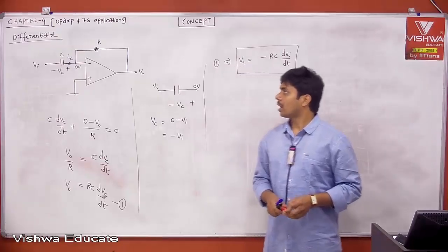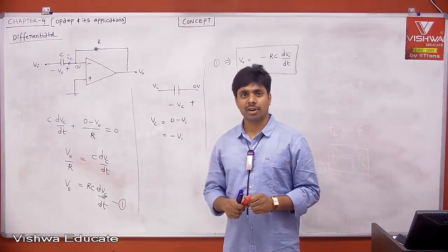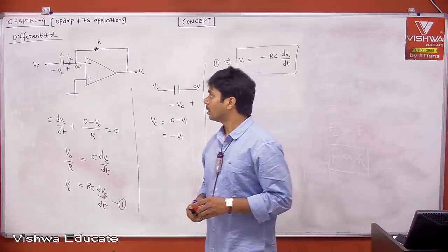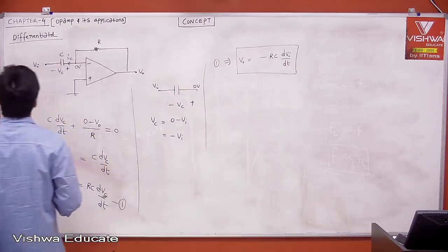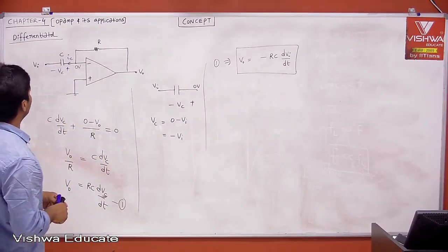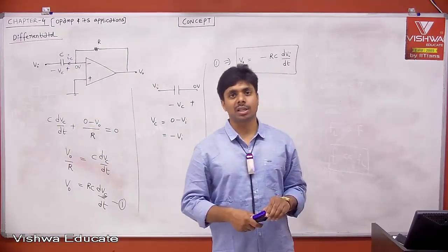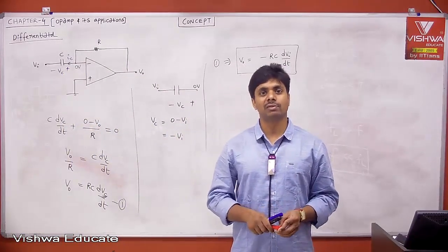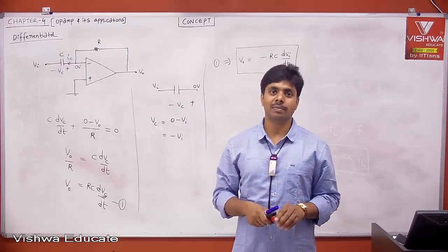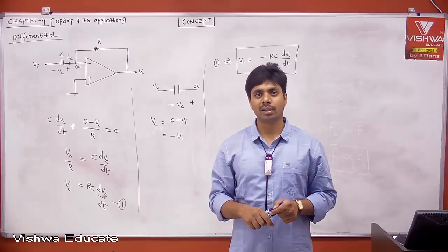That's fine. Now, in the last session, we covered differentiator. In previous sessions, we covered integrator, and while covering integrator and differentiator, I explained low pass filter and high pass filter, right? Then we can use low pass filter as an integrator provided the frequency of the input signal is very much greater than fh. Then high pass filter can be used as a differentiator provided the frequency of your input signal is very much less than fl, right? That's what I told.